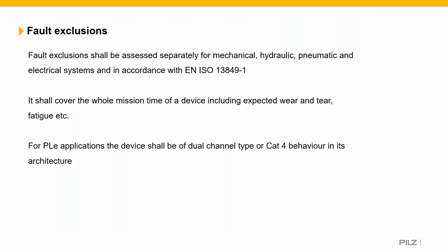They need to be assessed separately for the energy forms, so mechanical, hydraulic, pneumatic, electrical, etc. It needs to look at the whole mission time of the device, including any requirements that might be related to wear and tear over the course of its applications. And for PLe applications, it shall be dual channel or type category 4 style in its behavior or architecture.